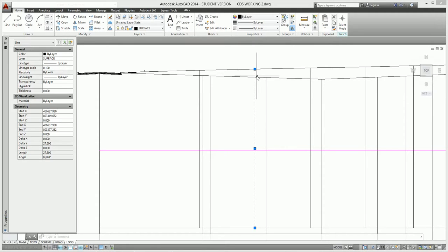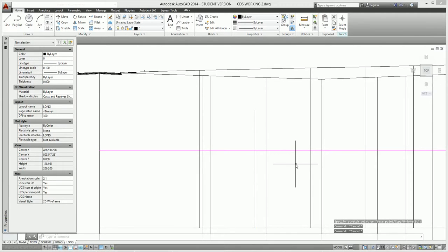Let's just say I draw in a random line through there, and I use the len command, or length, L-E-N. Okay, I'll put that length in, and then I use the total one, and then I say I want it to be 27.6, and then it asks me, and I just select that there, and it puts it in at 27.6, like that.